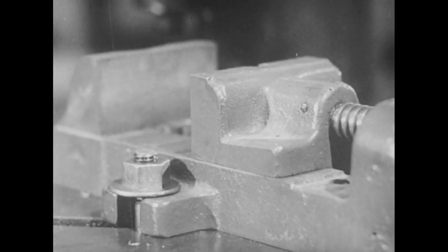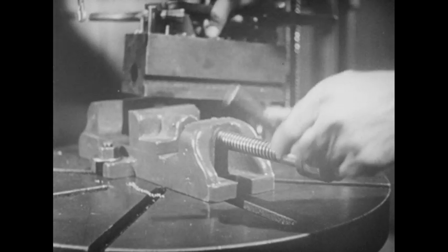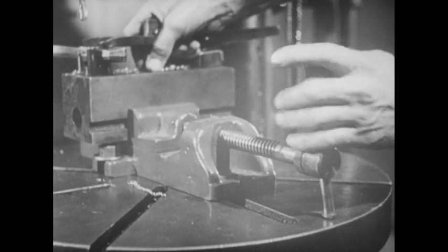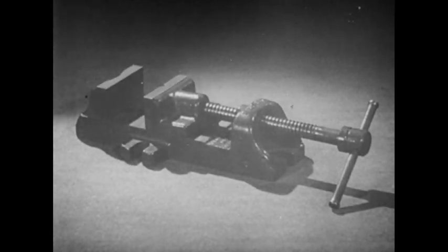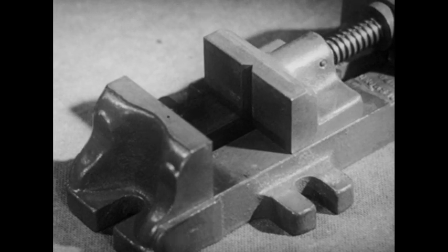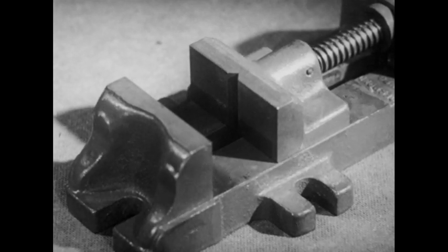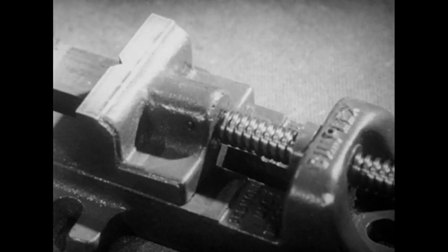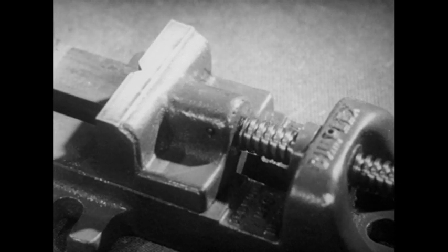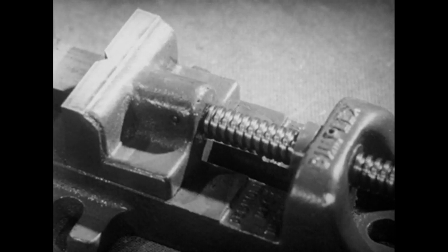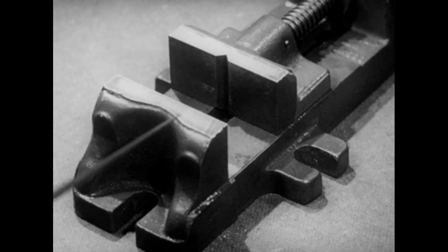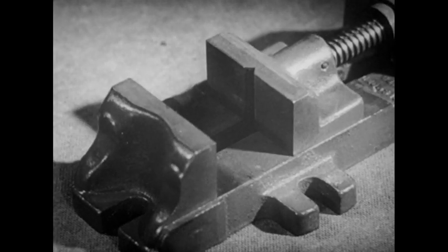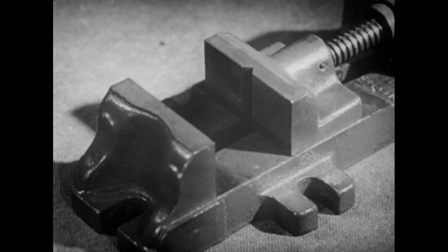Notice how the vise works, how the jaws move, and how the fixture is held between the jaws. Since you are going to dimension the movable jaw, notice how it fits with other parts of the vise, how it fits closely against the bed and yet slides along, and how the threaded shaft turns in the hole. Think about the movable jaw and its mating parts carefully, for these parts must fit exactly, though the dimensions of the outside or air surfaces are not so critical. Consider other dimensions of the vise also, where they affect the functioning of the movable jaw.